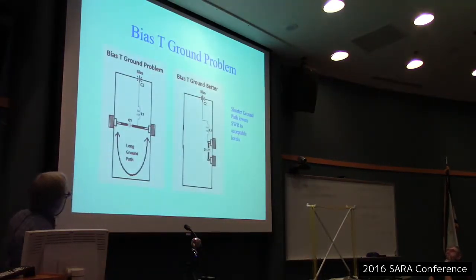This is another one that I ran into. It was a bias tee. This one was actually used in a ham application at 432 megahertz, but it's exactly the same problem as 408, but a transmitter signal went through it. You had a small capacitor between 2 connectors in a box, and then a choke to feed a DC voltage. So this would feed DC up to an antenna mounted preamp, and this would go to the transceiver, receiver, whatever unit it's hooked to. But this was just put in a box, and the path between the grounds on these was somewhat longer than the path going across here.